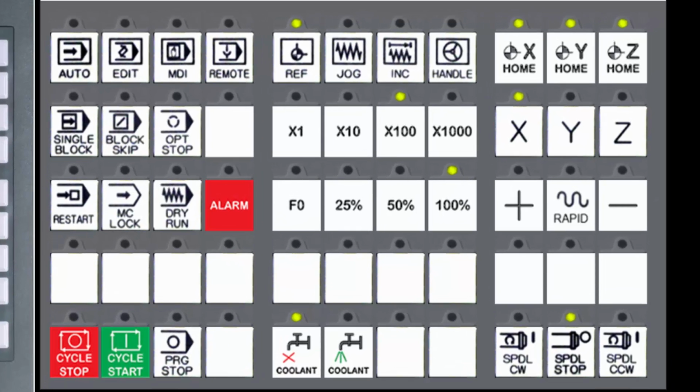Though the machine operator's panel is developed by the machine tool builder, many of the buttons, switches, and lights provided are a necessary component to run every FANUC CNC. These elements must be integrated with the machine tool features for safe operation. For example, cycle start is the button that the operator presses when they want to execute the selected part program. FANUC cannot predict all the situations that must be checked on a particular machine tool to determine if it's safe to allow the cycle to begin. There will be door interlocks, operating pressures, machine mechanism positions, and other things to check.